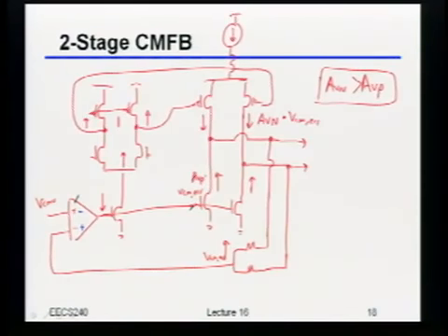Okay, good. So like I said, the key point here was really just that, when you do multi-stage amplifiers, as soon as you got multiple stages, you can't just worry about the stability of the differential mode. You got to worry about the common mode as well. And a lot of times that can involve a lot more subtle issues than what you might at first expect. But in particular, the other thing I want to remind you is that anytime you end up with these multiple feedback loops, where one's positive and one's negative, which by the way we'll see happening a whole lot more in a second, you got to make sure the negative feedback loop actually wins.